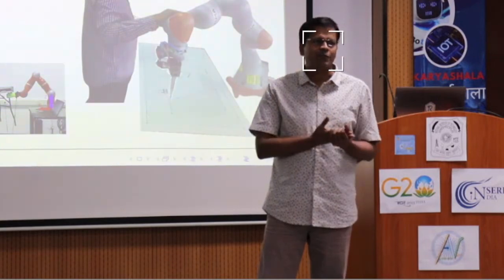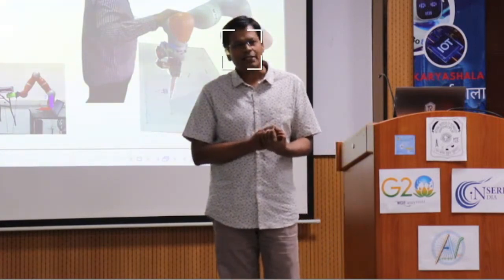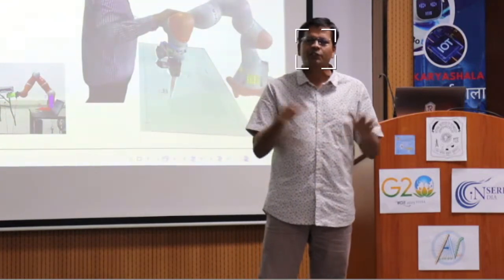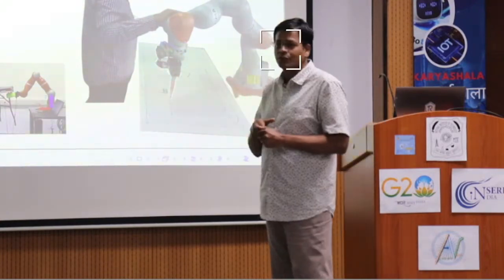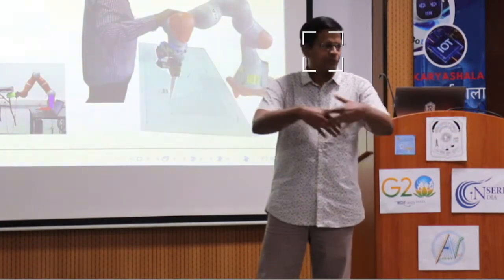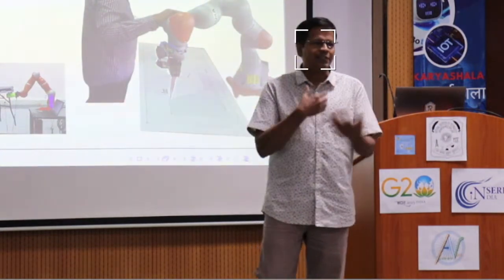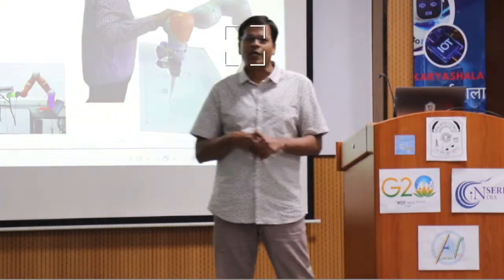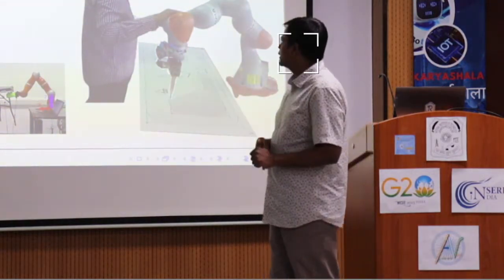So now with cobots, quite a number of times you don't need huge robots to do that job. Payloads of at least 5 to 10 kg, even 20 kg, can be easily handled with a smaller robot. Cobots nowadays are meant to work along with the human without any potential safety systems all around. Humans do exist with robots and work along with them. There are different levels of collaboration that each type of robot allows. So that is what we are going to cover in cobots.